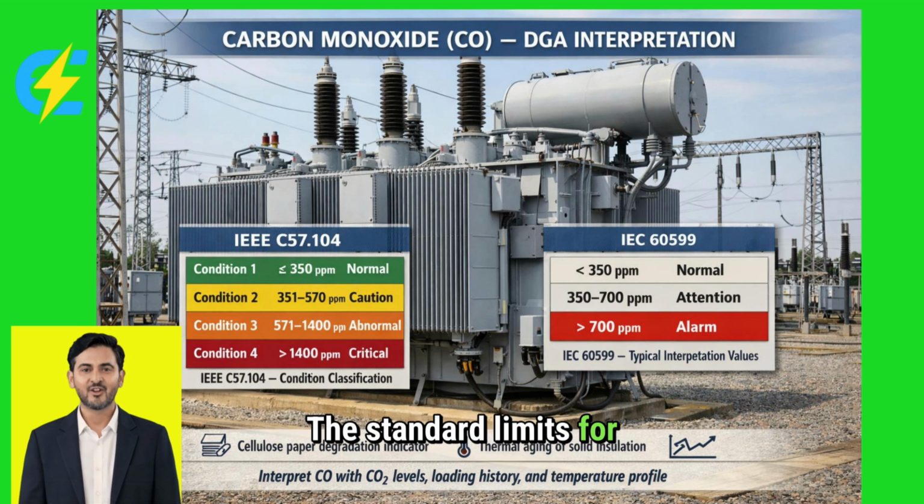The standard limits for carbon monoxide are quite specific. For normal conditions, you want to see carbon monoxide below 400 ppm. When it's between 400 and 600 ppm, you're in the caution zone. This is where you need to start paying attention. Above 600 ppm indicates abnormal conditions that require immediate engineering action.